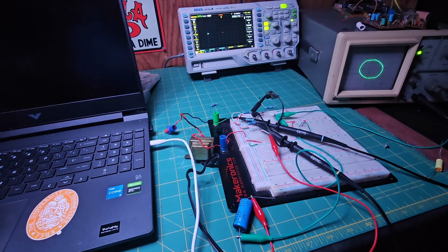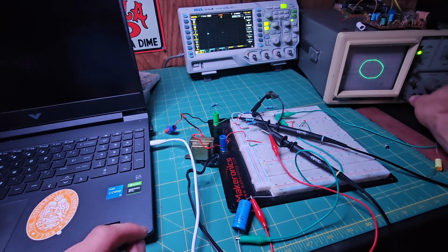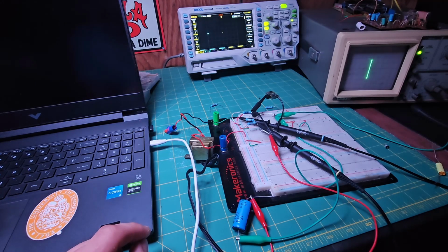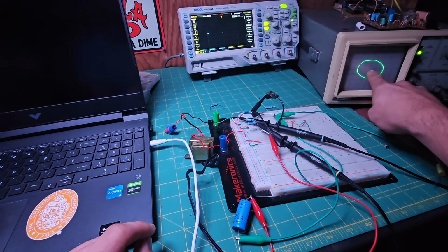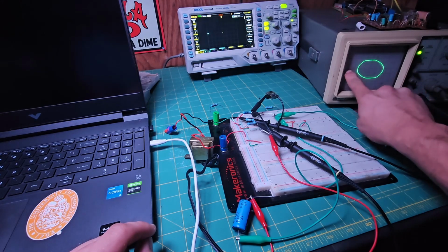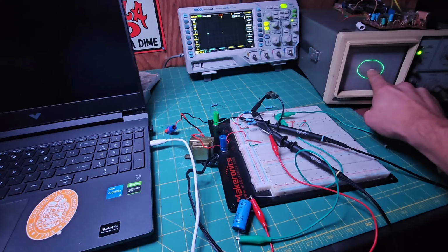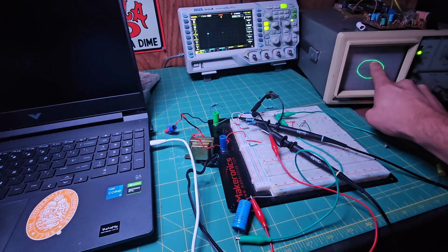And it was exactly the same as what I was just describing to you in Desmos there. So since IC equals C times dV over dt, when you have a sine wave that's being applied to this, it will draw the most current at the 0 point. And you remember when we removed this probe, the line is close to the middle. So when we remove that probe, that tells us that the 0 point on this scope, so the very center of that scope, is the middle of the sine wave. And so the outer edges are the peaks. So when you're in the middle of a sine function, that's when the derivative and therefore the current is the greatest.